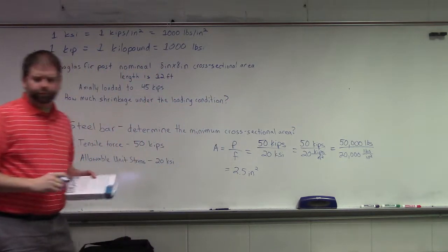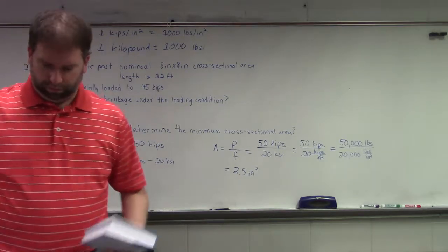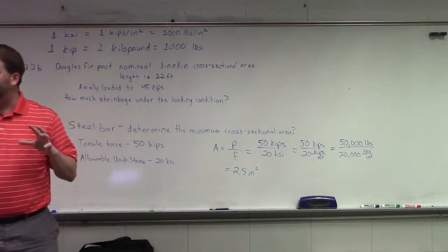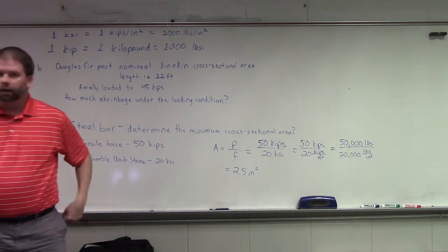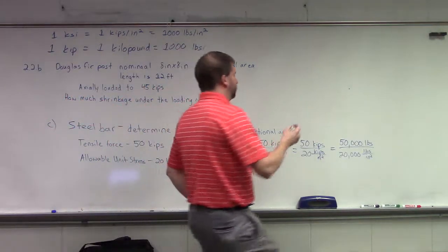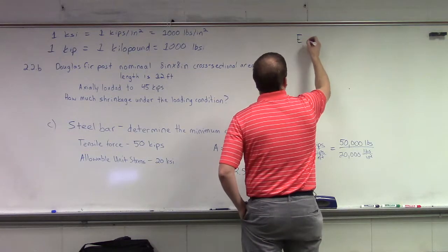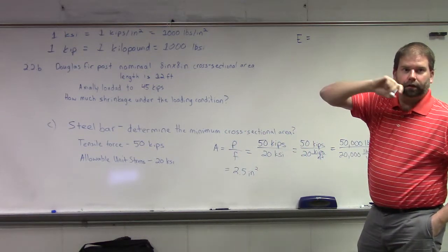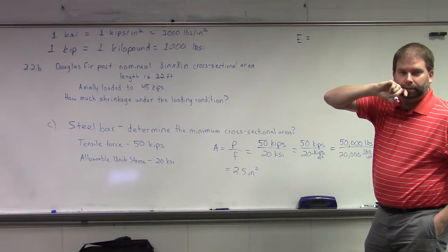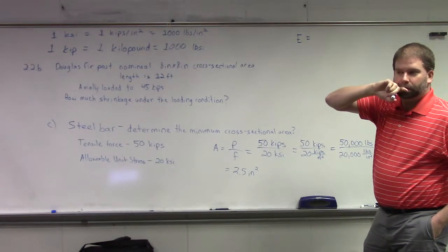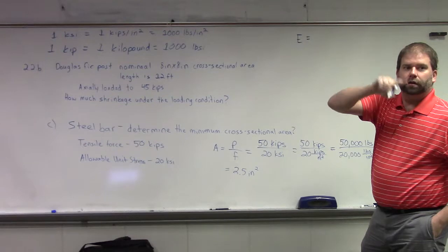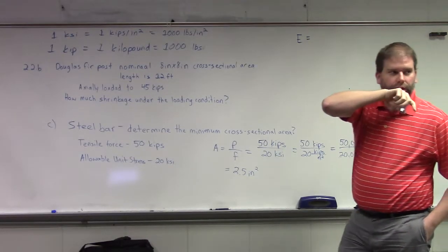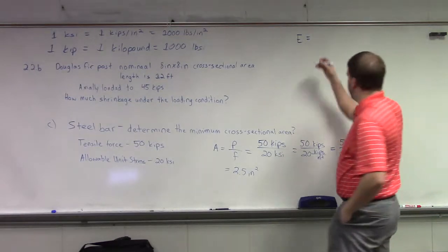Okay? So, before we jump into this one, let's take a step back. What's the base form of our equation? How do we determine the modulus elasticity? Are you doing the E one or the change of length one? Let's not jump to the change of length just yet. Force over strain. Yep.